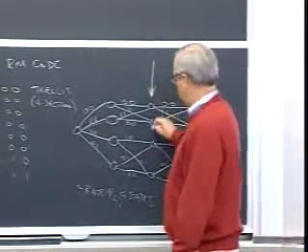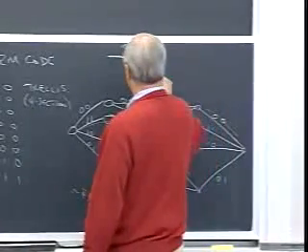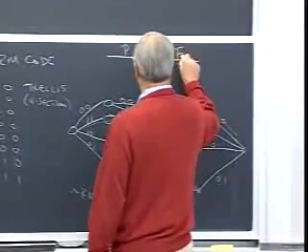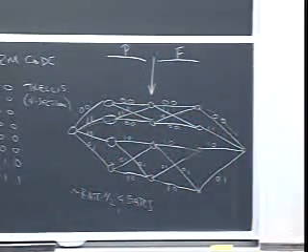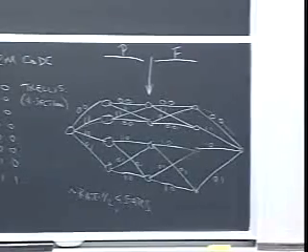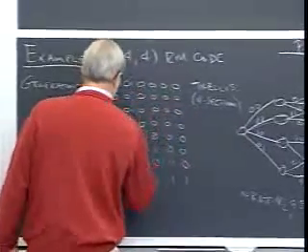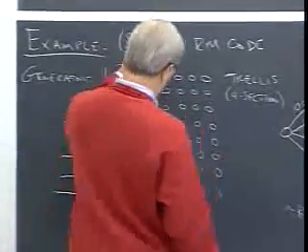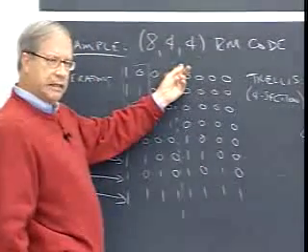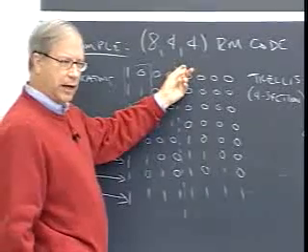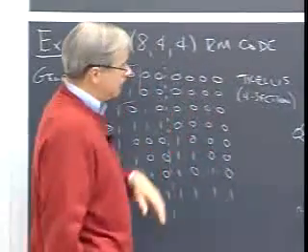You can think of a state as being associated with a cut between a certain set of symbols, which we call the past, and another set of symbols, which we call the future, again using system theoretic temporal language. All right, so if we make a cut, let's say, and do it over here, states are based on cuts between a past and a future. So the state actually occurs between the fourth and the fifth symbol here, not at either of them.